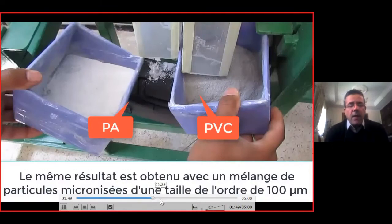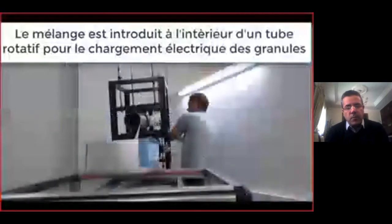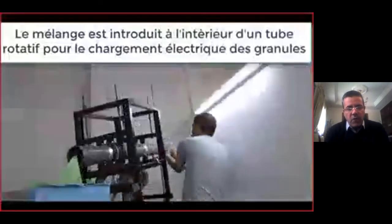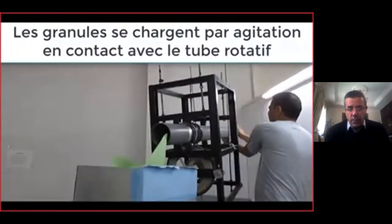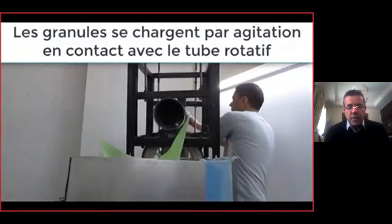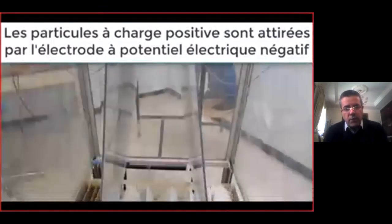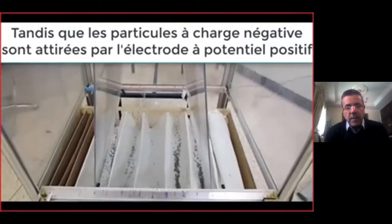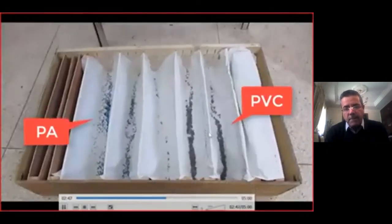This is another separator. What I showed is a rotating cylinder, and we put inside the mixture of our plastic particles. They are charged inside the cylinder, and at the output of the cylinder they fall down in free fall between two high voltage electrodes. And here you can see the separation by colors. Here green and here blue.